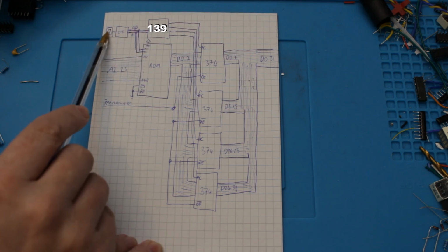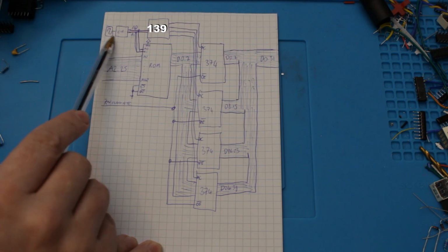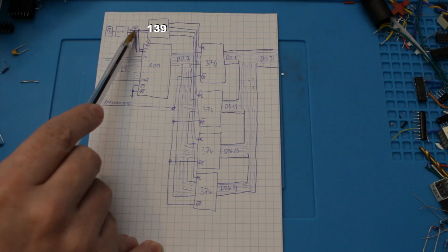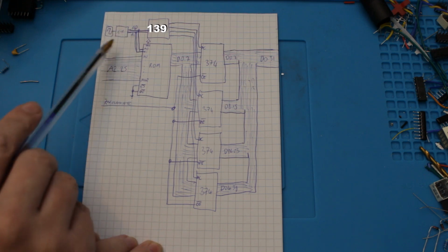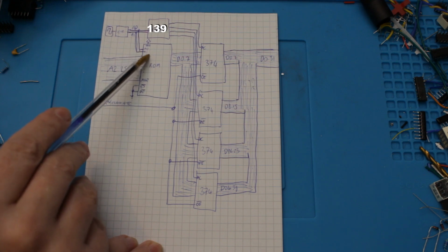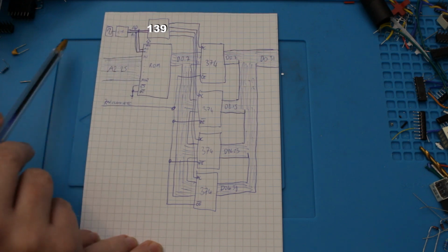We need a faster clock going into this system so that it can tick multiple times per bus cycle. We need a counter, and the counter is going to drive the A0 and A1 lines, which do need to go into the ROM, because the ROM is storing 4 separate bytes for each word from the CPU, so its A0 and A1 lines do need to be fed by something.